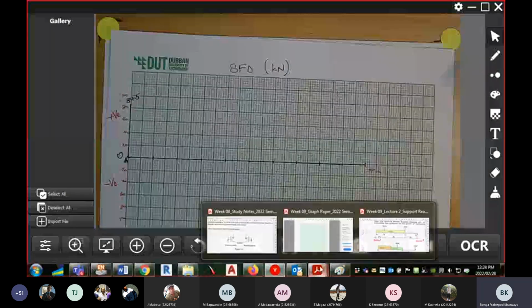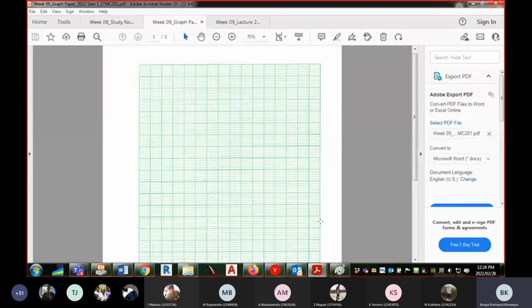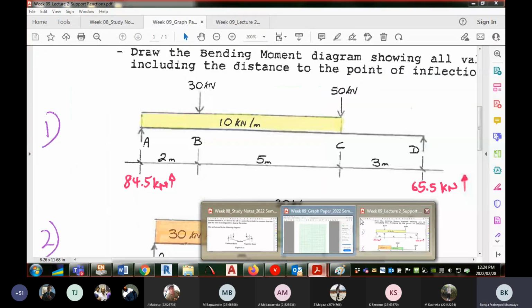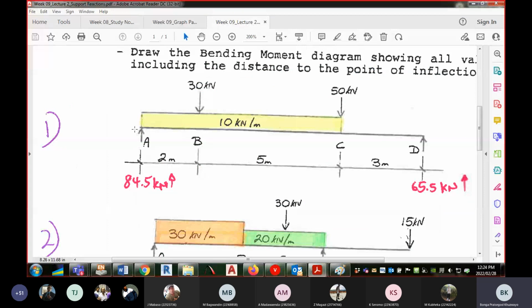And then remember, this is a graphical communication of how your shear forces are in your beam. So we just need to do a graphical representation. Basically, you do it where there is a change in load, or a sudden change in load, at the point of interest, where you might want to know the shear force at that particular point.